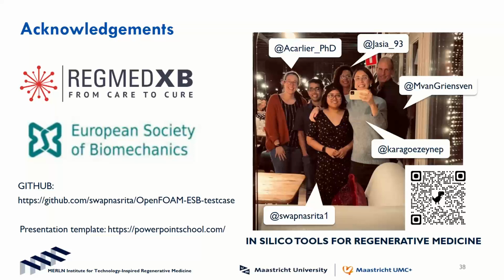Which types of non-Newtonian fluids? Basically, you can define any kind of viscosity. I think it's called viscosity dependent on material. You can define that and then it can solve it for those non-Newtonian fluids. There are also solvers available for non-Newtonian fluids itself. I think icoFoam is one of them, so you can use that for your non-Newtonian fluid. And pimpleFoam is also used for non-Newtonian fluids.